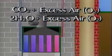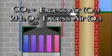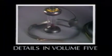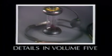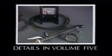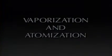Oxygen that is not consumed during combustion stays in the excess air that passes up the flue along with the carbon dioxide. These instruments read the outputs of fuel oil combustion and guide you in adjusting the burner based on the excess oxygen or the carbon dioxide, along with smoke and heat. You'll see how to use them in Volume 5.